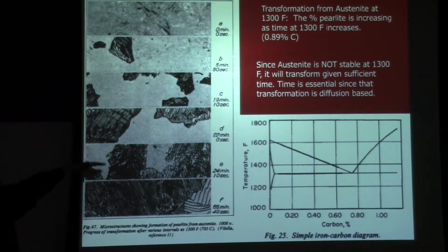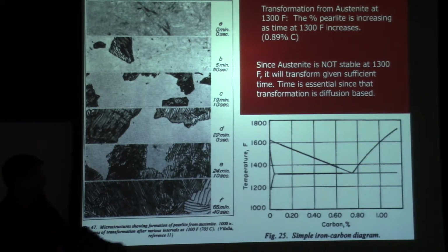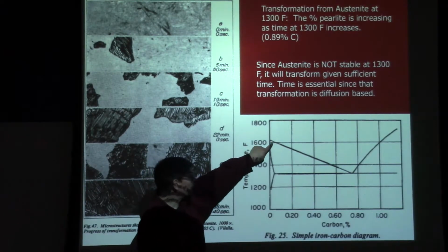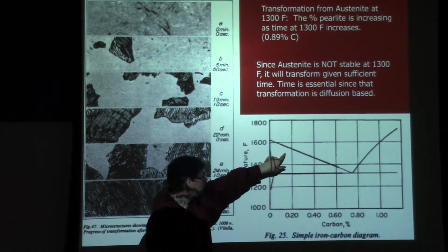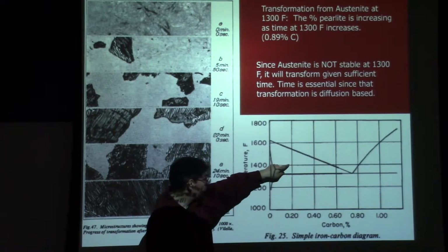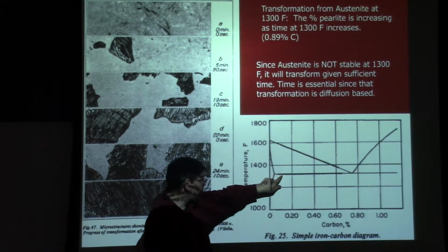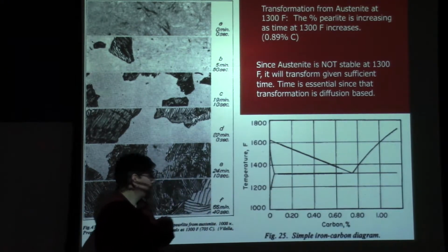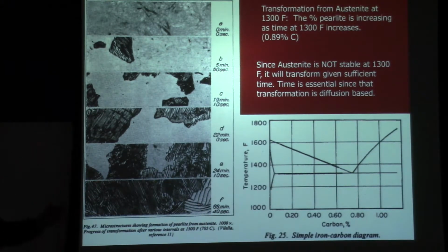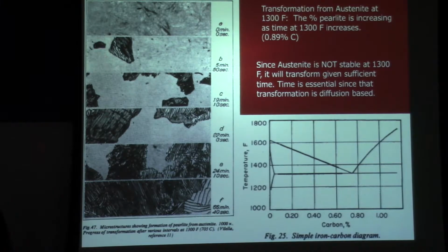So you can see this widely varying set of microstructures. We can see over here that if you were fully austenitized here, and you cooled down to just under this line, that's what we're talking about doing, and then hold for some period of time, and then quench, okay? We got this just vastly different set of structures.